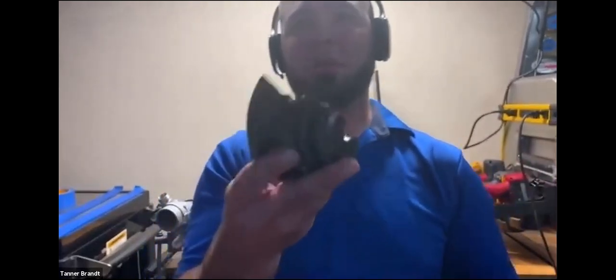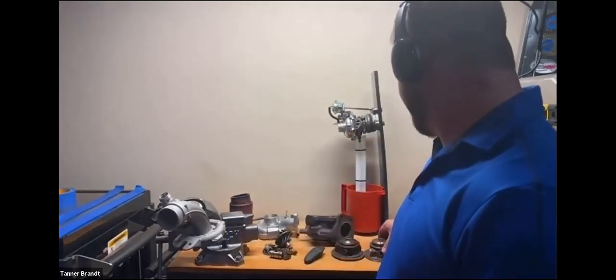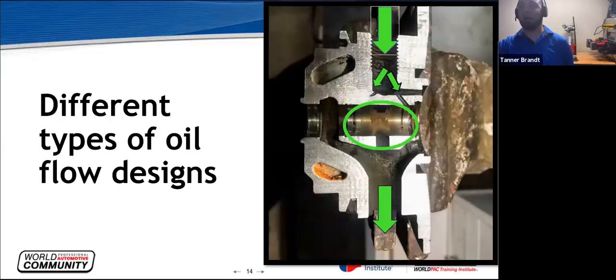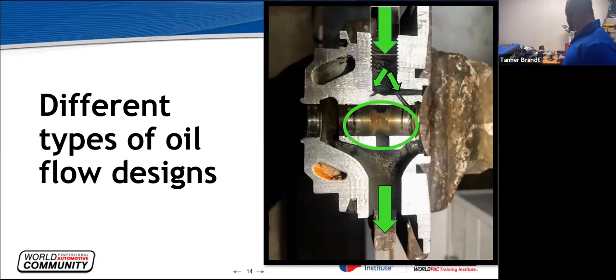So the only way to end up with coolant and oil mixing inside of a bearing housing is if this bearing housing were to crack, which I personally have never seen happen, and I've probably rebuilt in the realm of, I don't know, 10,000 turbos when I was doing it full time. So I've never seen one crack. So it's very unlikely, if you have coolant mixing in a turbo, that you could have a bearing housing problem causing it. So just keep that in mind.